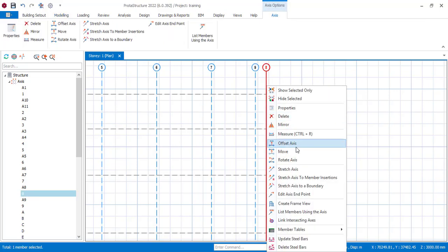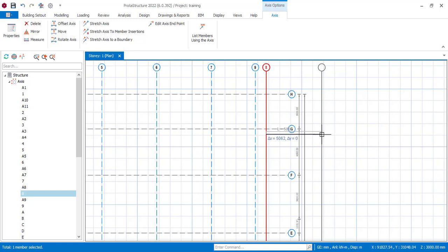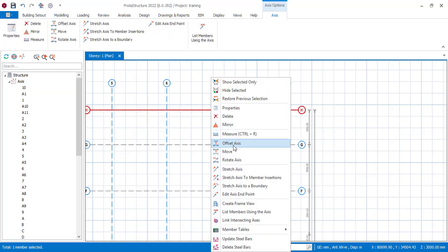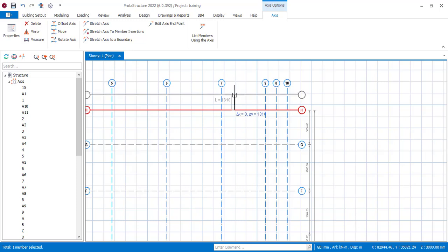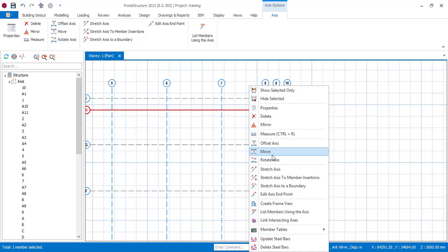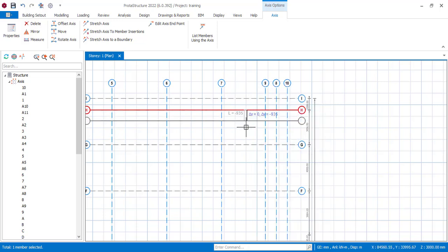Similarly, if I want to offset forward, all I need to do is hold on Ctrl F2 and type 1 meter. I don't need to type in plus, because whenever you are going forward, there is an invisible plus in mathematics. I'm sure most of us are familiar with that. So basically, that's how to achieve that when you are going forward. If you are going upward, upward is positive, downward is negative. Going right is positive, going left is negative. So that's basically all you need to know about this.